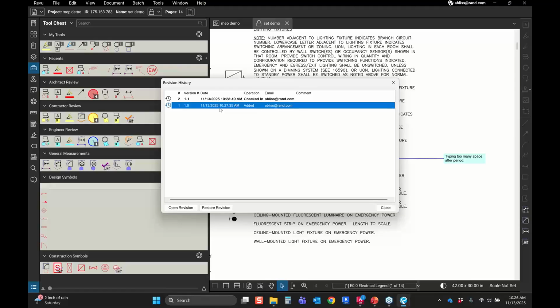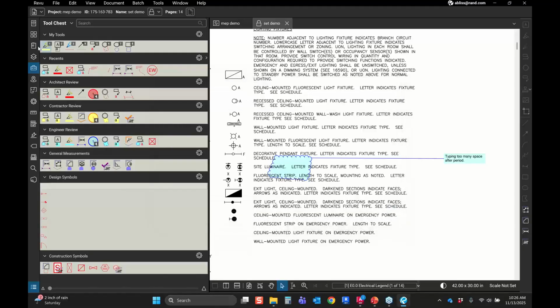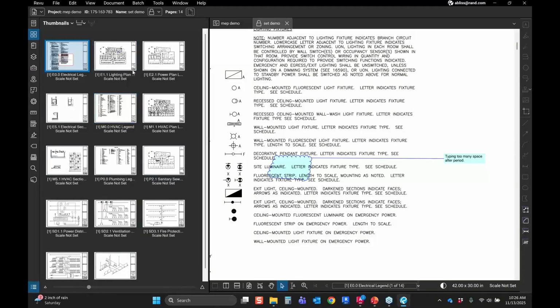Which is really good. If you're getting updated sheets, you can quickly slip those sheets in, doing a similar thing like I did: drag and drop those sheets in, and then check it out, drag and drop the new sheets in if those two sheets got updated, and then save it and check it back in. And then you can note, I updated sheets 2 and 3, and that's what's in the revision history. So you never lose anything with this.